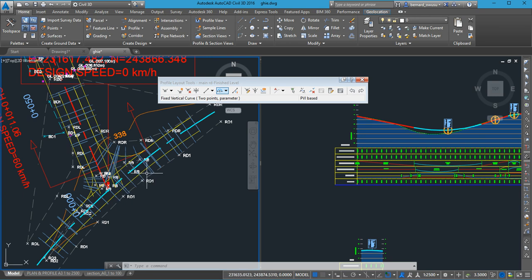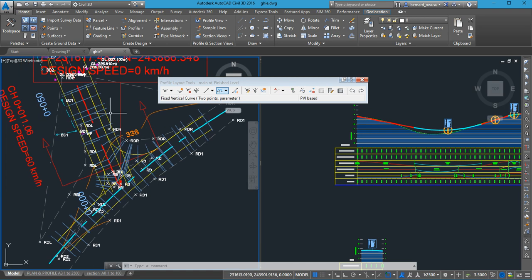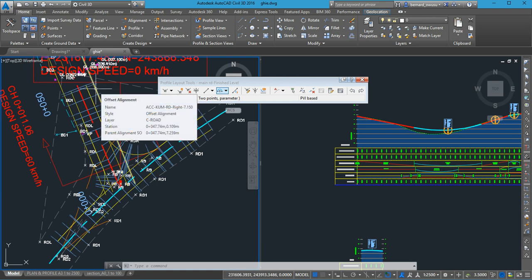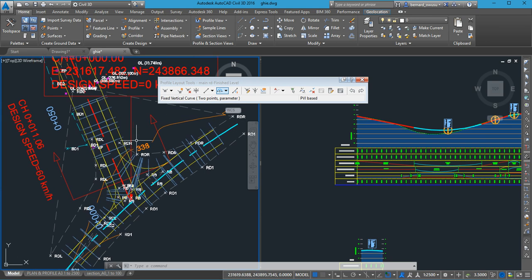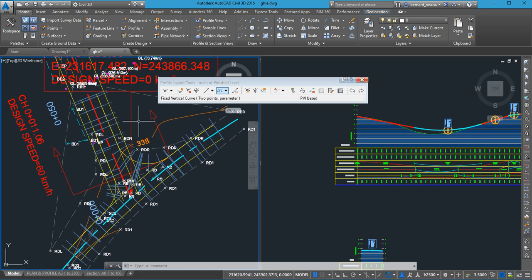But you inserted the corridor. Yeah, yellow has come. Okay, try to regenerate and let's see what will happen. When you were creating it, before it came here, did any warning sign come, maybe about the secondary profile?